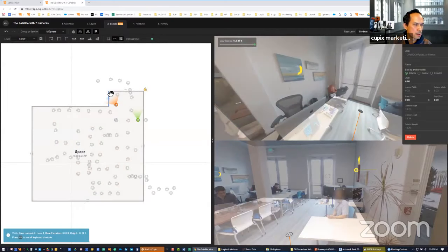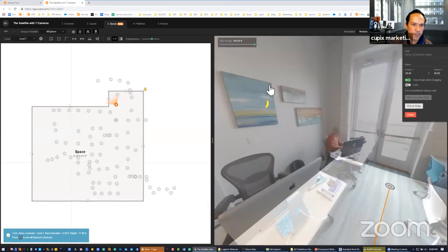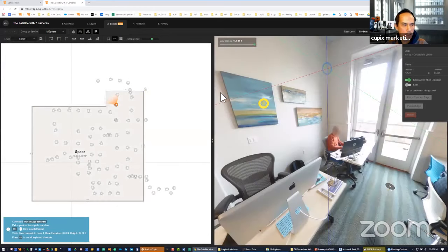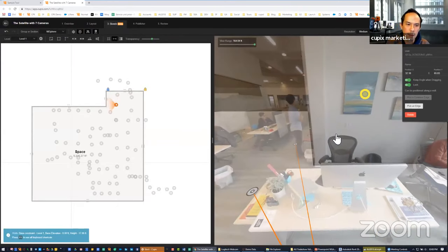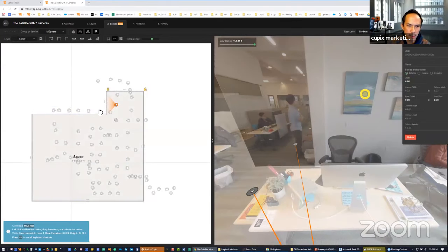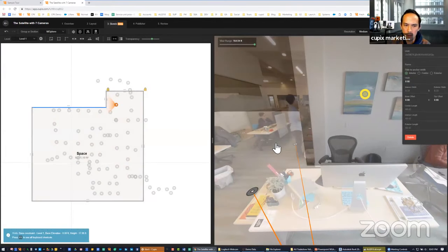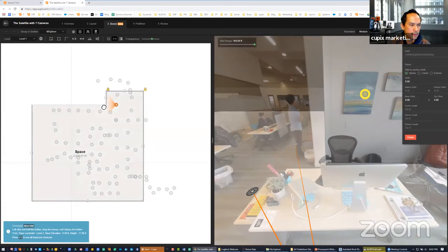But what I can also do is use a single pane here so we're more focused. What I can use is pick a common edge, and since this edge is locked and this other edge is open, I can just pick that edge, and that defines where that location should be. So just a single click, in exactly one click, you can define where a wall is supposed to be. Looks like I got a good guess right there. If I wanted to model some of the intricacies of this beam, I could definitely do that.